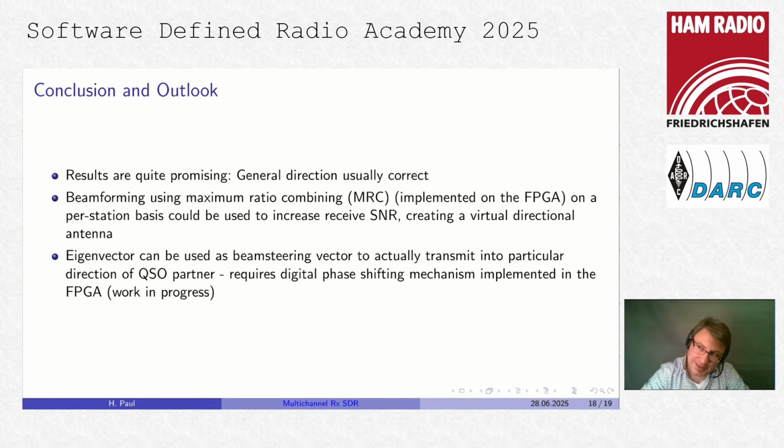But that, of course, implies that I'm able to control the phase of my transmit signal in a rather fine, granular way. And this is usually where it gets tricky, but I have already something in the works now. A scheme with which I can at least coarsely shift the phase of my transmit signals. This is currently work in progress, maybe something for next year's SDR Academy or the year after that.